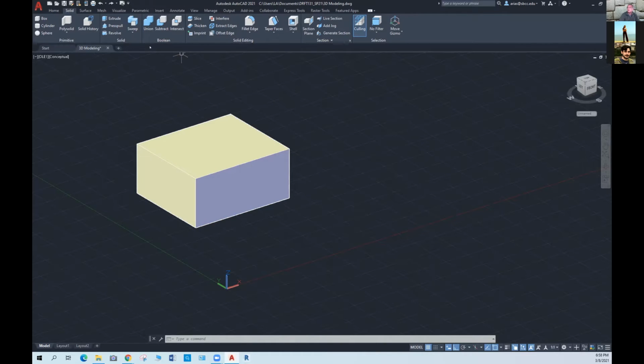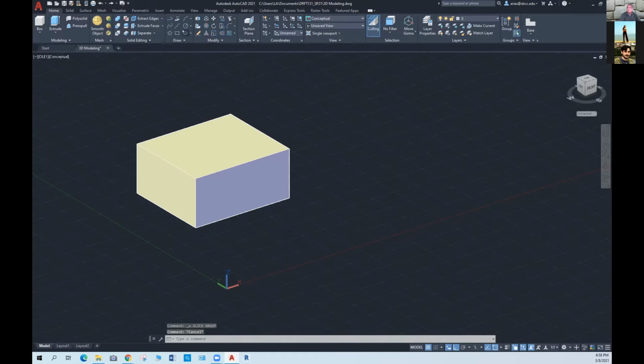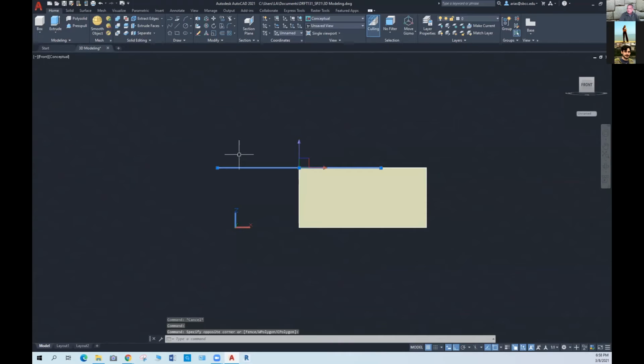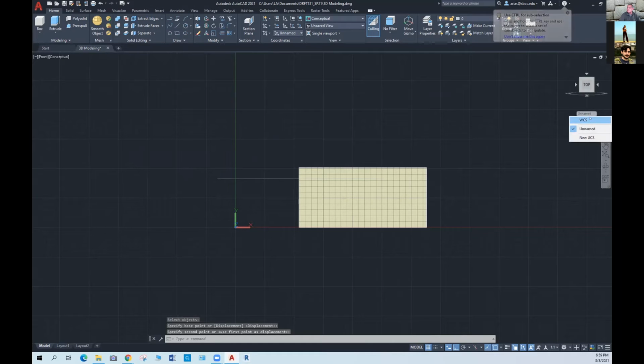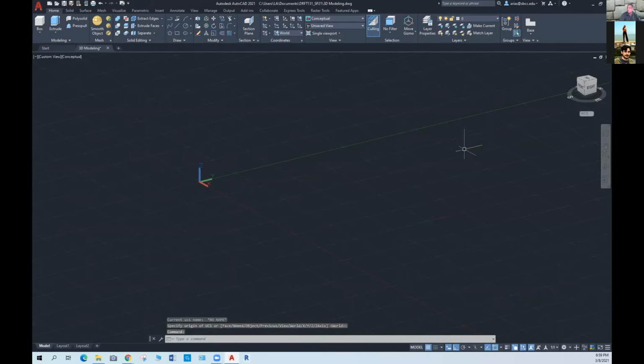For example, I like sometimes to use the circles to do slices. Right? And so if I move that circle down, I can go to the front side. This is a circle, right? I can do UCS by view and now move the circle down. Now I can go back to World UCS, 3D, go home.